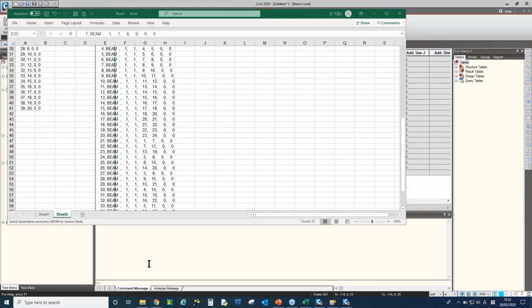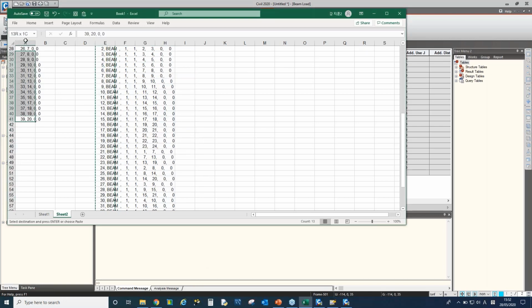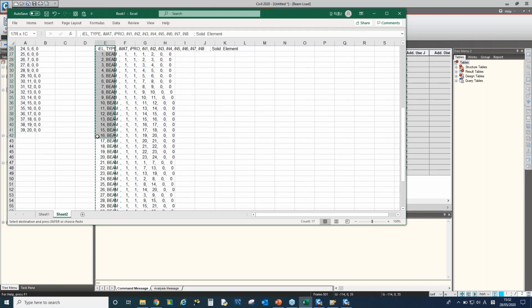Can I define a crossbeam like a box girder section by using an Excel sheet and the coordinates? To generate the element, firstly, we need to have the node first, and then when we generate the element, we need to include the node information to be connected to each other.